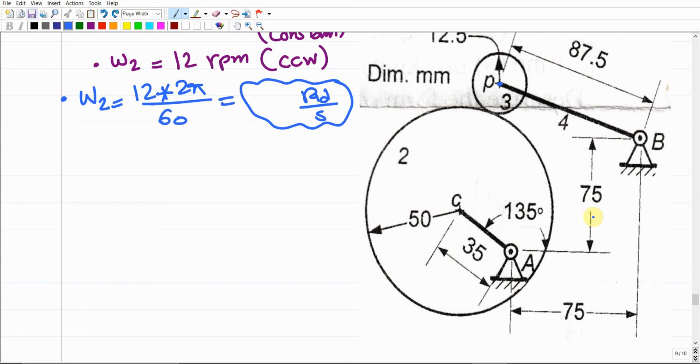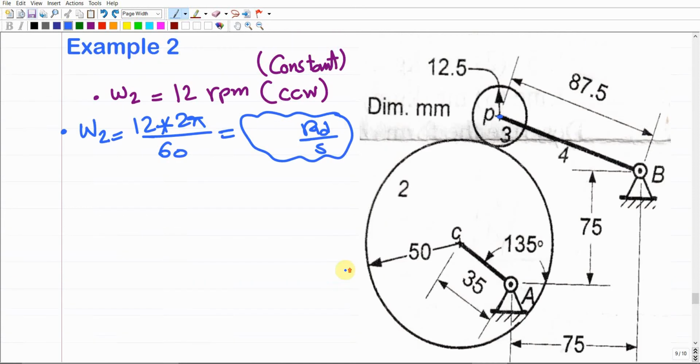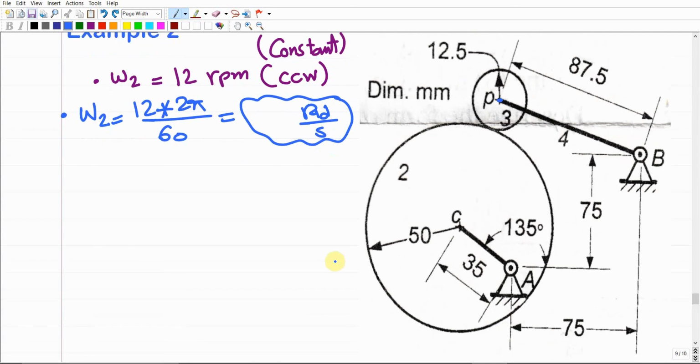Again, it is required to do a complete position, velocity and acceleration analysis for this mechanism, and find some of the velocity components for point P and point C, whatever the requirements are in terms of velocity and acceleration. Anyway, there is an essential or arbitrary loop that we have to assume or consider for this mechanism. This is a rolling contact problem. We have to convert it into an equivalent direct contact problem so we can handle it. So how can we do this?